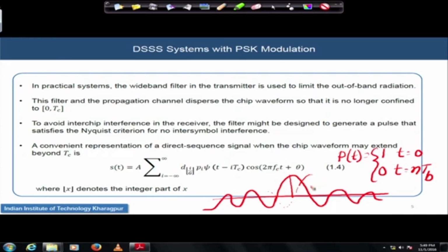So, you are getting a peak value when others, its corresponding pulses, are not having any peak. The pulse that Nyquist took has places where it is minus TB and this is plus TB. So, this is twice the TB value, this is minus twice TB value, and TB is equal to 1 by RB, we will call RB the bit rate.